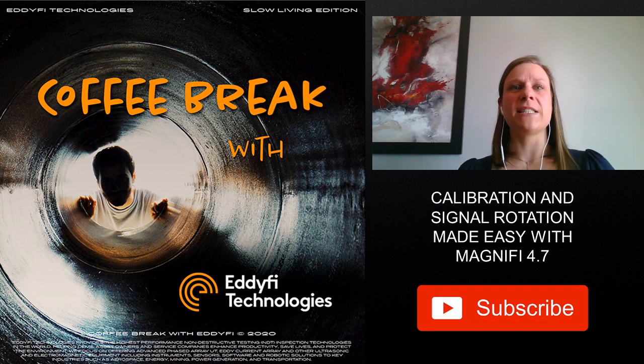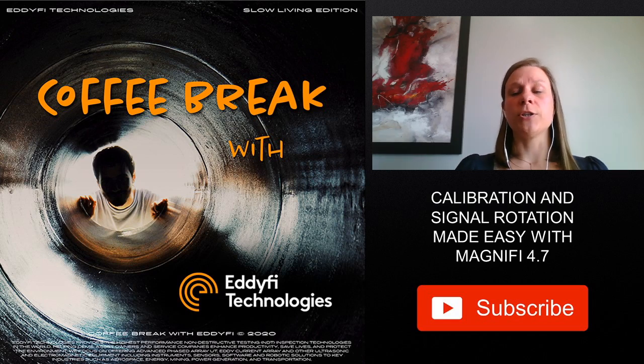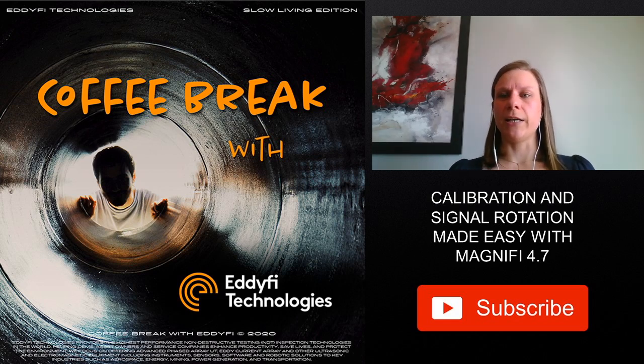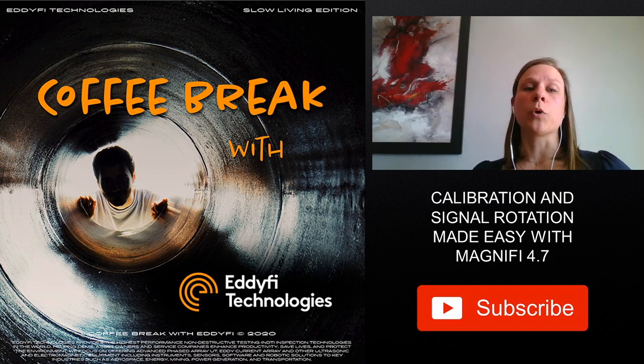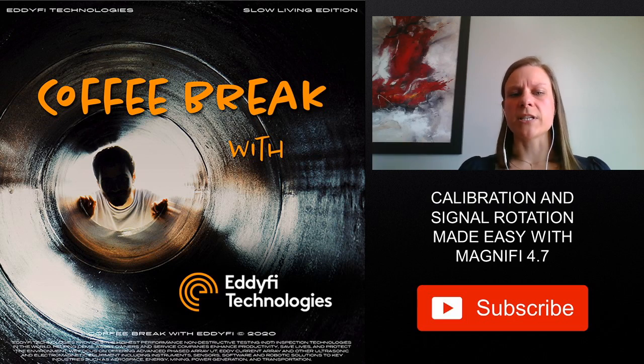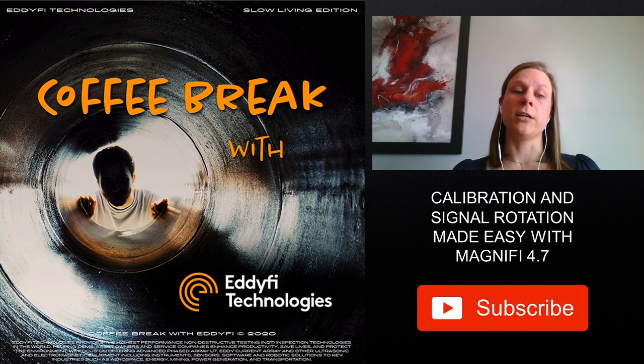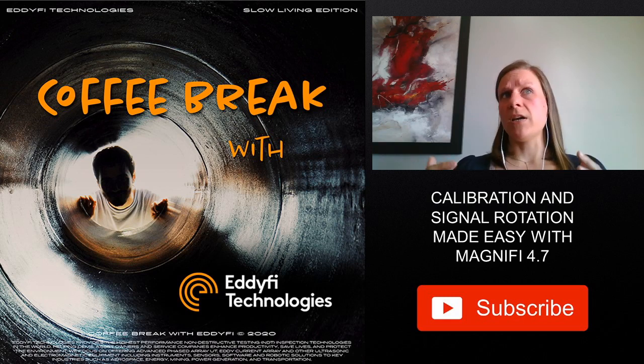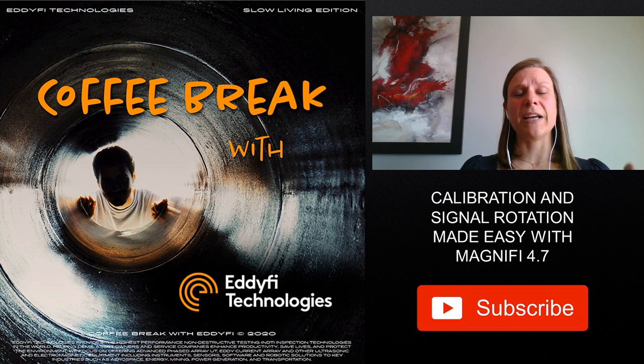Just quickly, my name is Anne-Marie. I'm product manager for the Surface product line. So the Surface product line at Eddyfi is mainly working with eddy current array. We have different product lines, but on our side, we mainly deal with solutions to inspect the surface of conductive material using eddy current arrays. We are addressing different applications or challenges, so it can be cracks, corrosion, pittings, even in some cases finding material properties variation within the material.